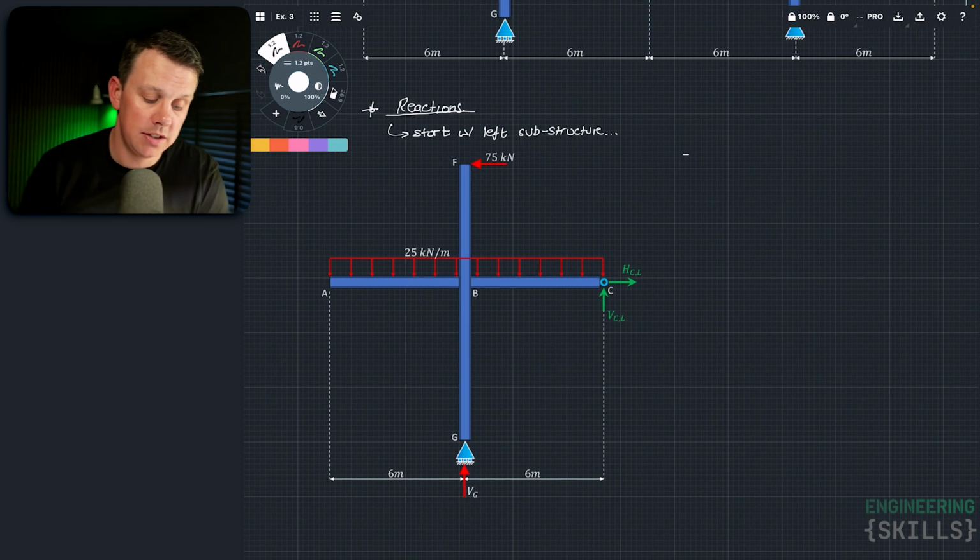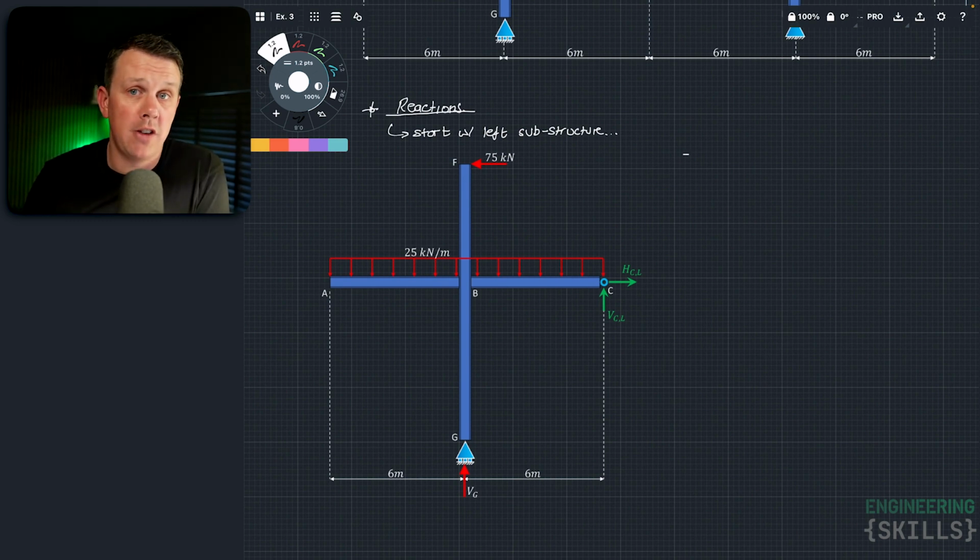Now in this case, you can see I've taken the force that gets transmitted through the hinge and I've broken it up, or divided it, into 2 orthogonal components, a vertical component and a horizontal component. They are just 2 orthogonal components of the single force that gets transmitted through the hinge. Typically, when we've broken beam structures at a hinge, the only force that is revealed is a vertical component of force, because typically it is only shear forces that are applied to our beam.